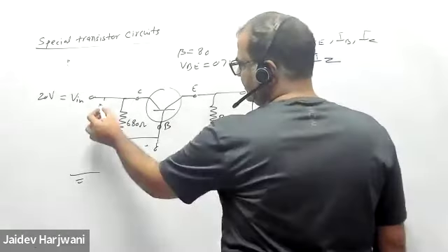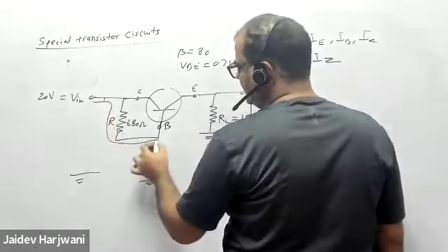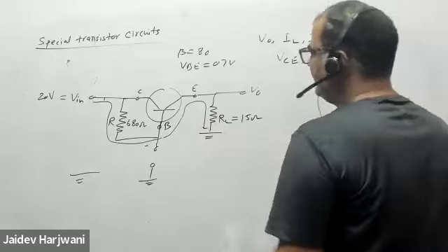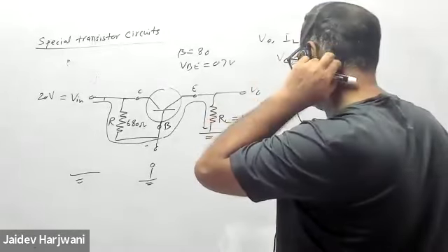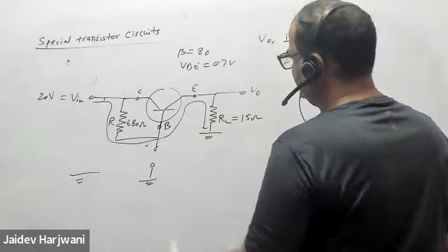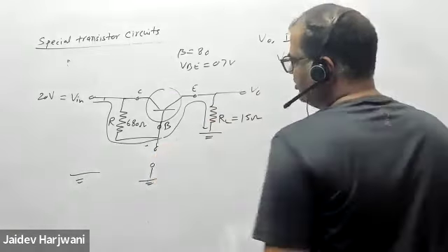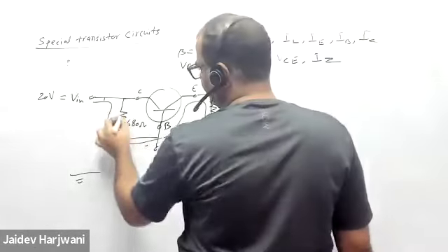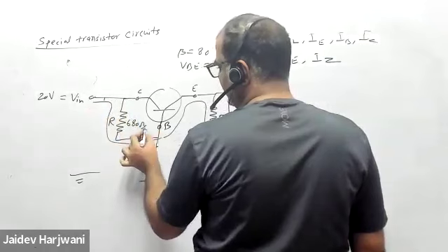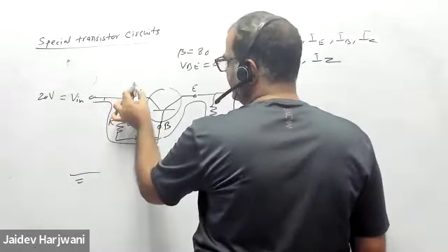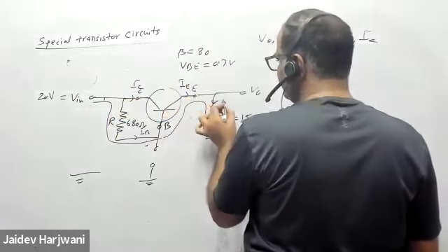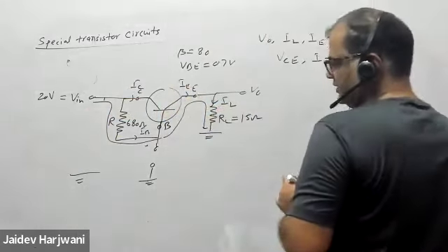Now, with the open circuit, the current will come here and you can directly go to here, and find the value of this voltage. Obviously this current will become IB, because this current is going here. IC is going here, and IE is coming here, and IE is what makes the load current.